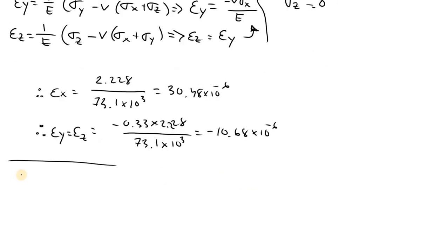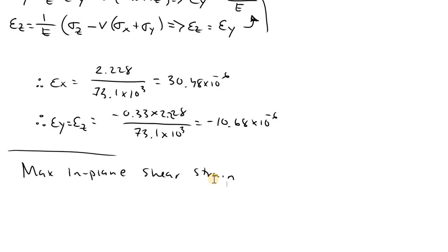The last thing we want to do is find our max in-plane shear strain, which is simply our maximum strain minus our minimum strain.